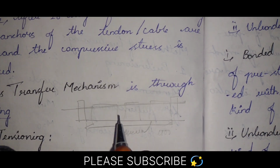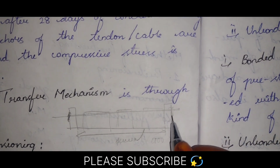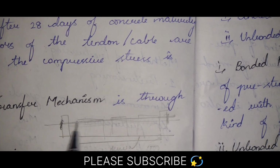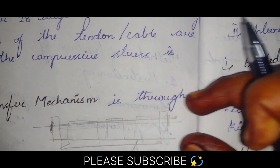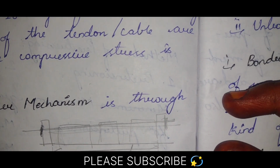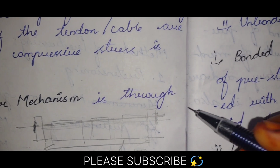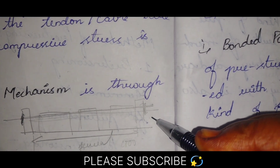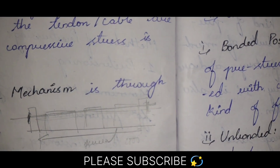This would be a fixed one, and here this would be a movable one. Till the required tension is achieved, we will be moving this. This is a movable one. Do you understand? The tension is applied by this hydraulic jack, or we can say a movable stressing machine. So wires are stressed until the required tension is achieved.